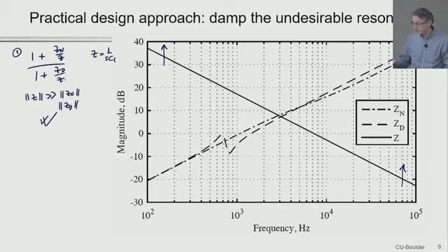Unfortunately, that's not going to work. No matter how large Z we make, we are not going to be able to avoid this interaction because, unfortunately, Zd and Zn are both inductive. As you go up in frequency, they are larger and larger. There's no way to remove that capacitance interaction with these inductances, except, of course, in the limit, you can just take it out. But if you take it out, this converter no longer works, right? So this is just not going to be an option. You can't remove the interaction by making the impedance much, much larger than Zn or Zd.